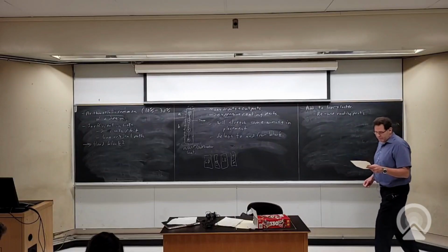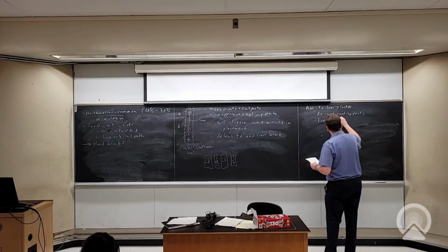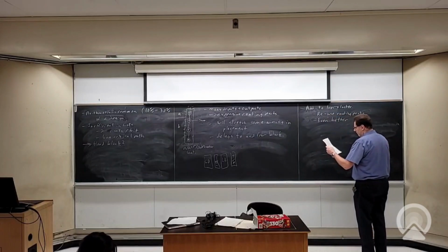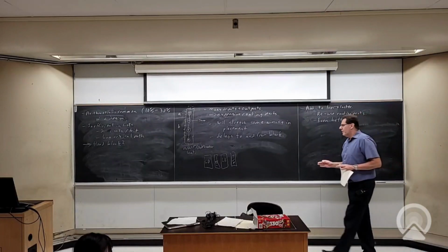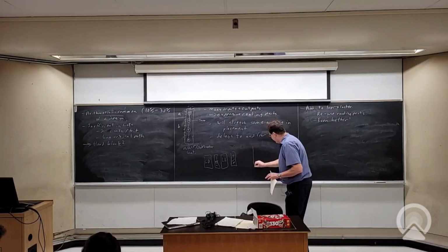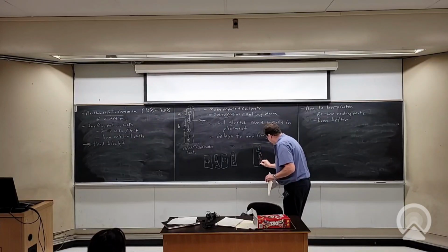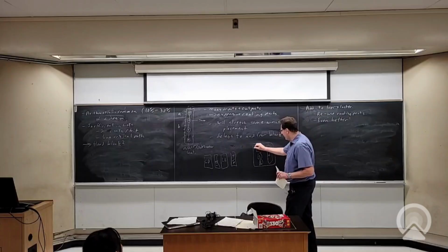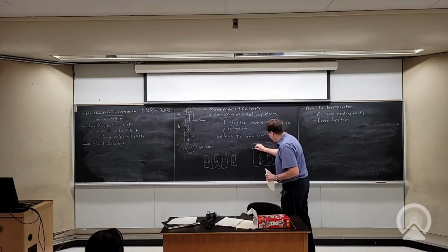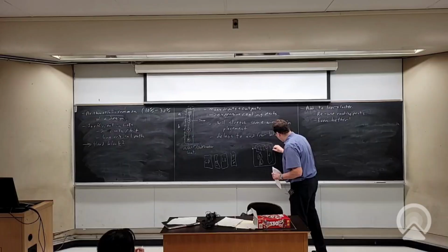But we can do even better. Okay, so that would be a better solution than what we had right now. But there's one that's even better that I'll draw. Which is essentially, let's just build the hardened structure. But instead of saying you use the adder, okay, so let me just show what we're talking about here. You could have LUT, LUT, LUT, and you could have this big adder. And we could say, okay, we've got some routing ports. They can go to the LUT, and they could also go to the adder, right?